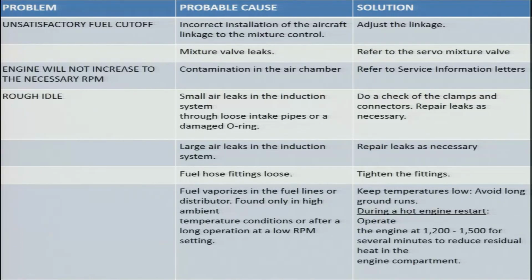Another problem is unsatisfactory fuel cutoff. Now, we have moved the mixture control from the rich condition to the idle cutoff condition, and still your fuel is not satisfactorily cutting off. In that case, the probable cause is incorrect installation of the aircraft linkage to mixture control. So, your mixture control linkage might not be correctly installed, and in that case we need to adjust the linkage.